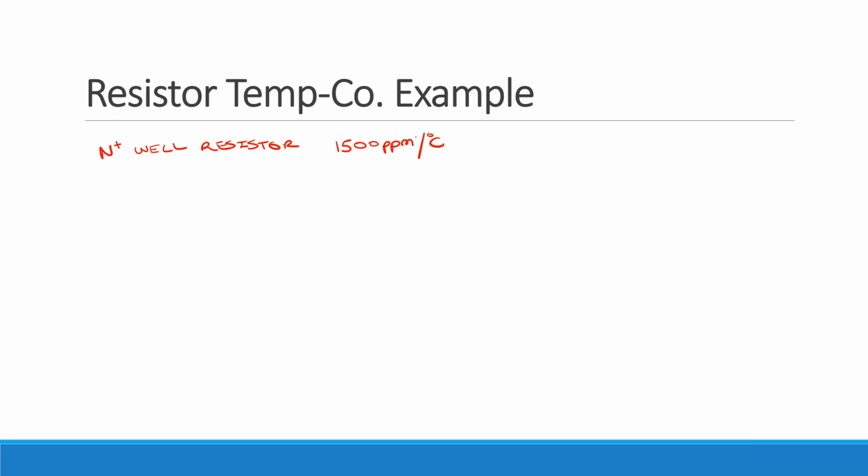So what would be a standard temperature range for you to deal with in ICs? Somebody said negative 40 to 80. That's reasonable. Any other thoughts? Or 0 to 70. Yeah, they're both about right. Minus 40 is pretty darn cold. If you're doing military or space stuff, you probably have to go down that far, but usually you don't go quite that bad in normal things.